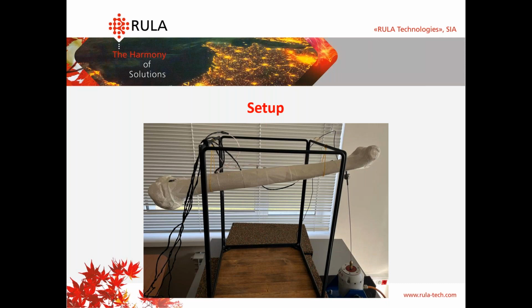We can also connect strain gauge sensors and set a measuring dimension for them. So in that case, you can set any sensor you want, and we don't limit the maximum sensor number. It depends on how many channels you have on your system. Today we will use 5 input channels of our controller, so it's not limited.